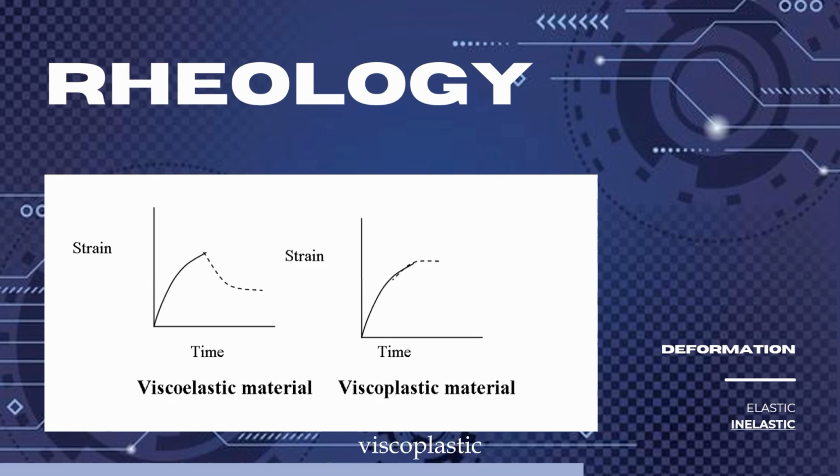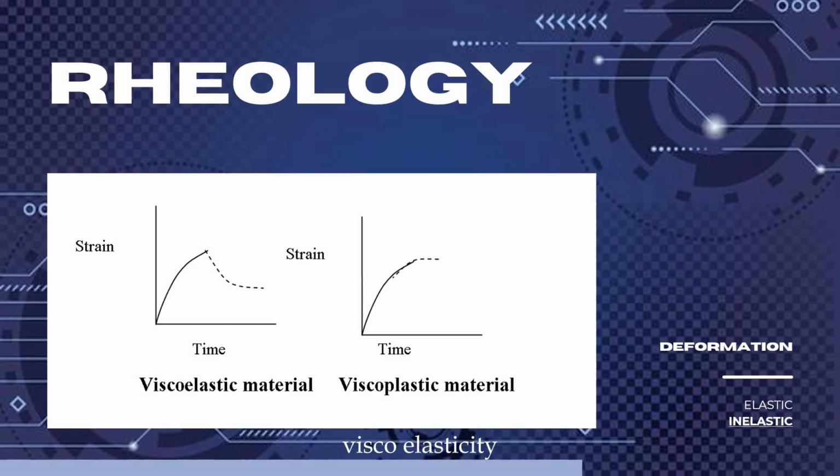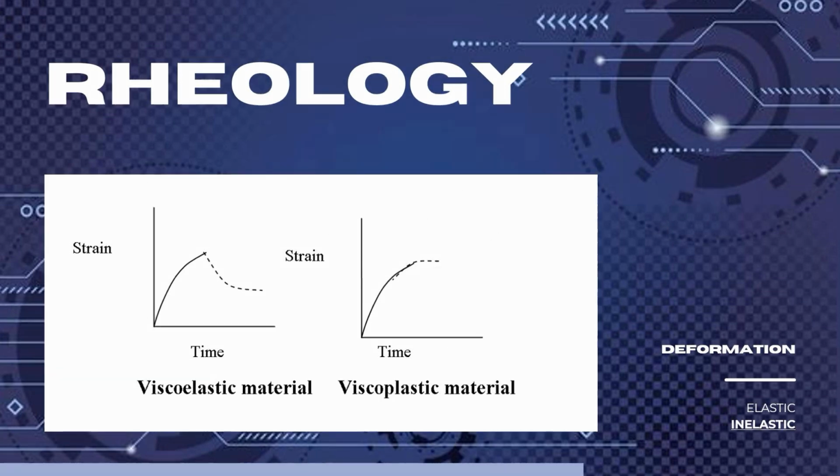Viscoelastic material and viscoplastic material. Viscoelasticity is the property of materials that exhibit both viscous and elastic characteristics when undergoing deformation. Viscous materials, like honey, resist shear flow and strain linearly with time when a stress is applied. Viscoelastic materials have elements of both of these properties and, as such, exhibit time-dependent strain. Viscoplastic materials are characterized by their time-dependent, irreversible deformation behavior under inelastic loading conditions, which is distinct from the recoverable deformation of elastic and viscoelastic materials.